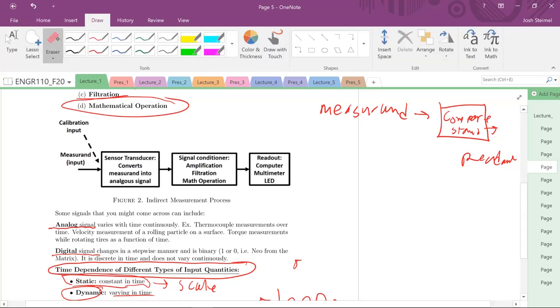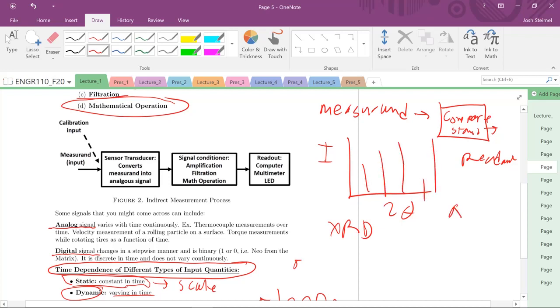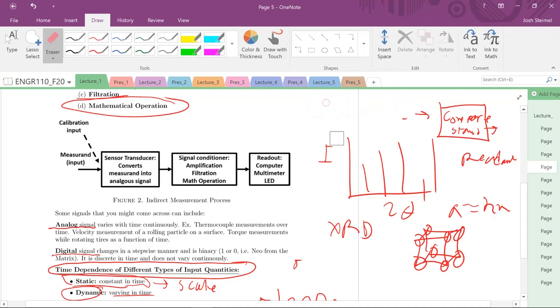The reason is that we are looking for high precision and high resolution in our experimental apparatuses. For example, if you're working with materials and you're graphing intensity versus 2 theta of an XRD measurement, you see peaks of different metals, and you're trying to measure the lattice parameter a to see whether it's BCC, FCC, simple cubic, etc. If you're taking my Engineering 45 course, you know this exactly. We're making measurements at the nanometer length scale. We can't do this by directly measuring against a ruler. So that's where direct measurements are more uncommon.